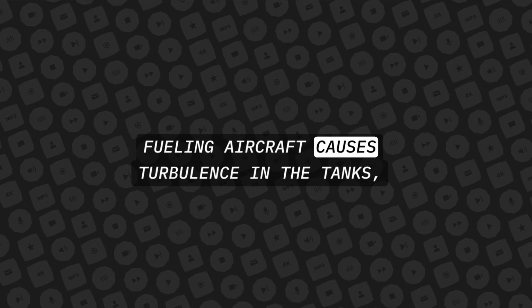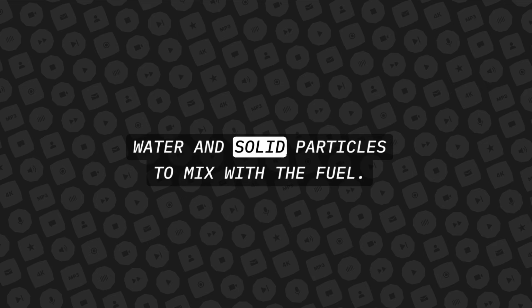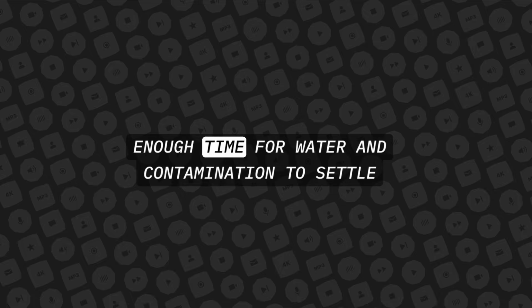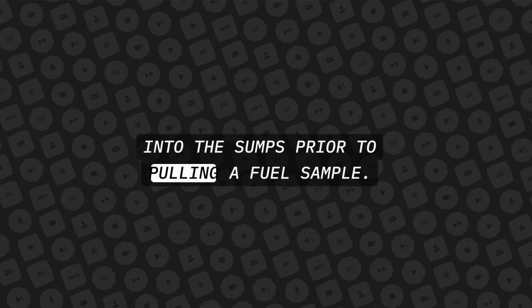Fueling aircraft causes turbulence in the tanks, which results in contaminants such as water and solid particles to mix with the fuel. It is important for the technician to allow enough time for water and contamination to settle into the sumps prior to pulling a fuel sample.